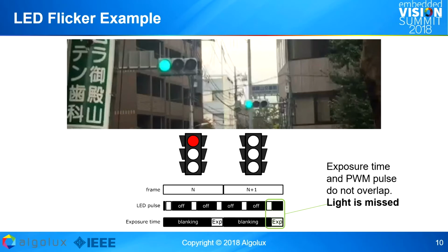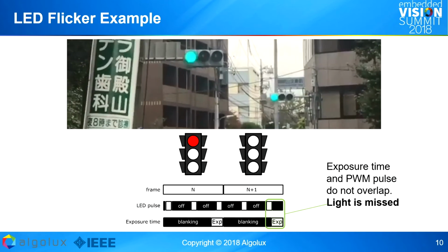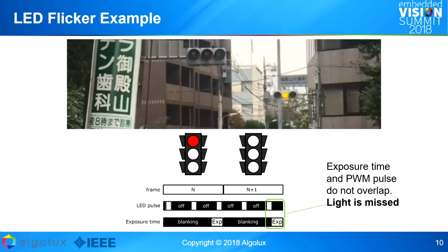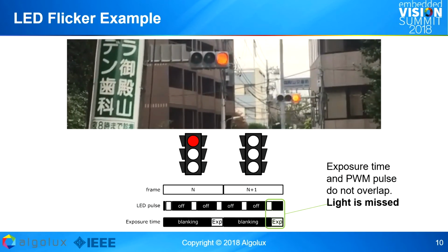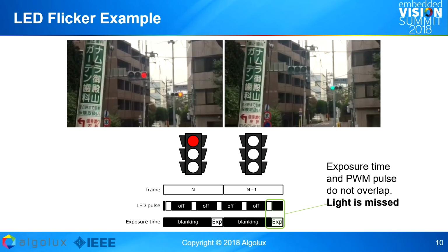So now if you have a short duty cycle exposure in your camera system, let's say like 30 frames per second, then something that is shown here on the top, an effect can happen that you miss certain of these pulses. And there's various different sensor technologies and ISP technologies to try to mitigate flicker and alleviate it.